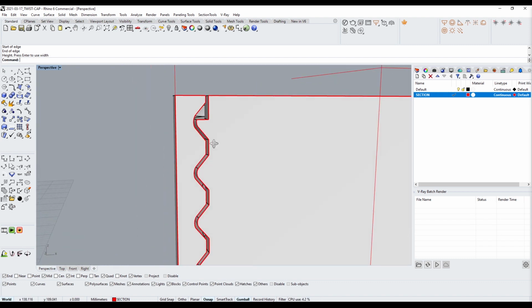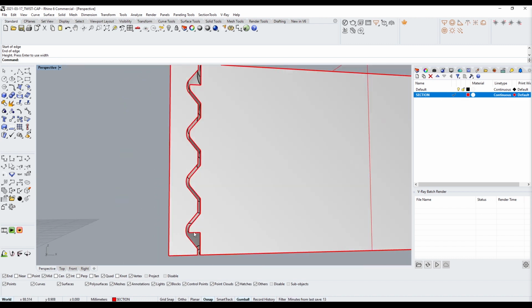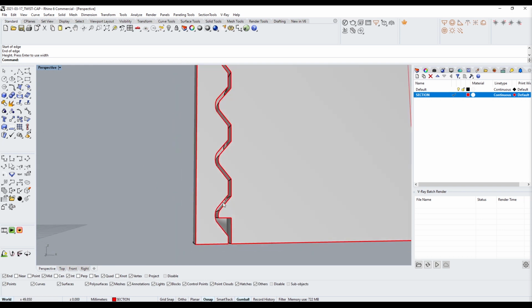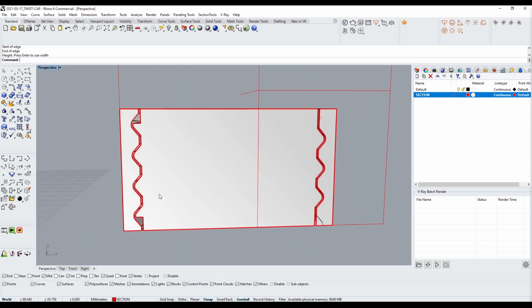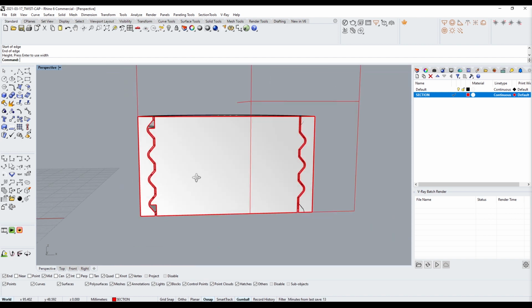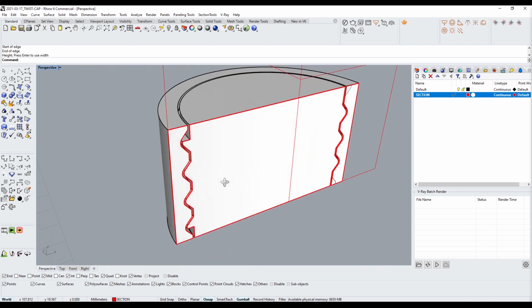And you'll see that we have the cap with some tolerance. What this will do is help you open it and close, and you can play around with the tolerance. There's a lot of variables when it comes to 3D printing. There's going to be layer height, there's going to be the speed, and the quality of how you print it is going to determine how much tolerance you're going to leave here. So with that being said,